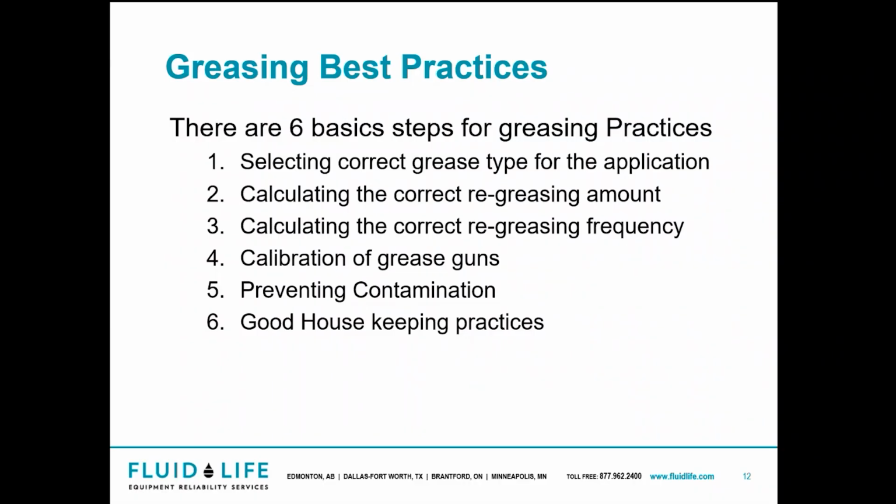So in this step, you're going to need to determine the type of grease for your application, right? So do you need lithium base, or do you need a polyurea, which is more typical of an electric motor? And then how much grease are you going to need? We're going to get into that a little bit in the next few slides, calculating how much grease and how often.